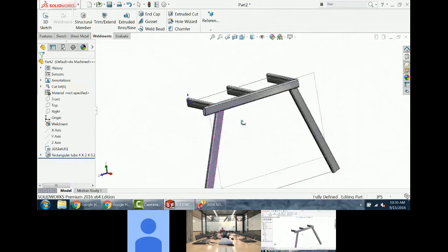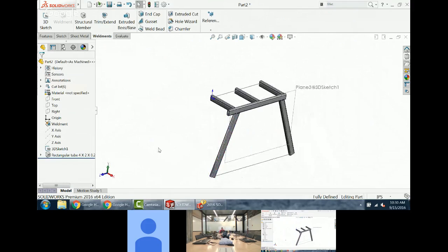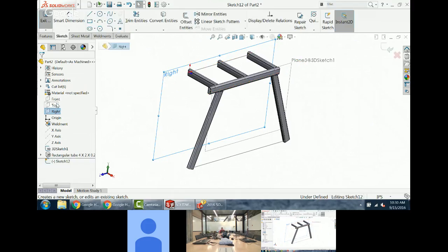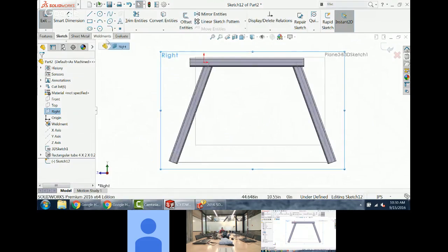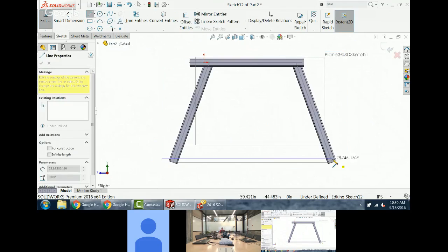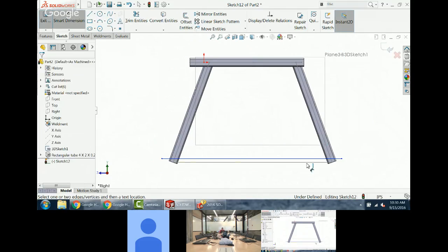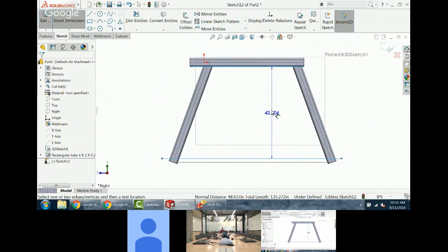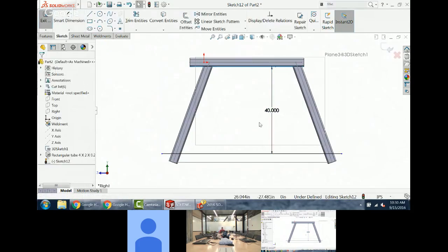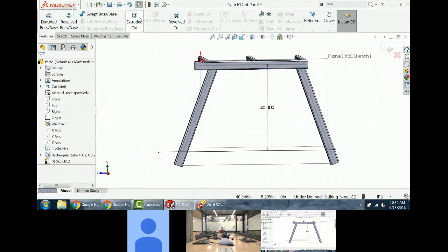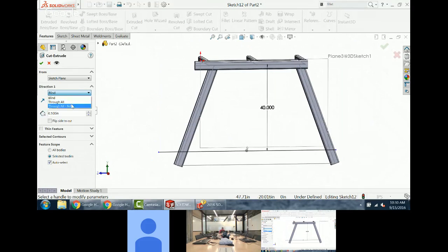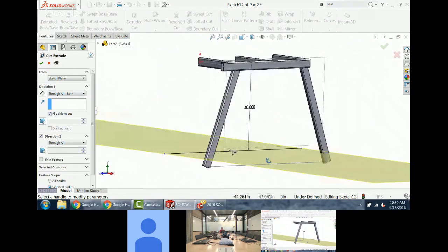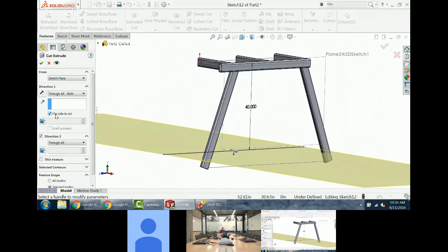The items that I want to fill out in here, I do want to cut some stuff away. There's different ways of doing cuts inside SolidWorks and inside Weldments. If I do an open contour, something like this, when I choose to do a cut extrude, it'll automatically cut everything to one side. I use this flip side to cut to determine which side it's going to cut away.